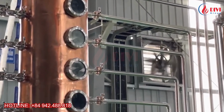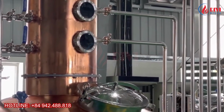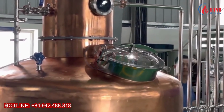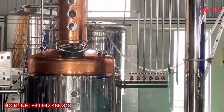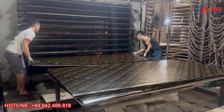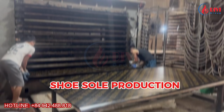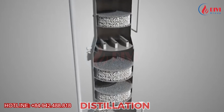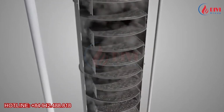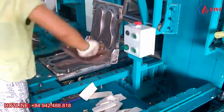Higher pressure means stricter equipment design requirements, greater safety risks, and higher investment costs. In contrast, thermal oil can be heated to 250 degrees Celsius, 280 degrees Celsius, or even 300 degrees Celsius, while operating at relatively low pressure. This makes thermal oil heaters ideal for production lines that require high temperatures without the need for high-pressure steam. Common applications include plywood production, hot pressing, shoe sole molding, mold heating, high-temperature drying, oil and chemical heating, distillation, and many other industrial processes. In hot pressing applications, maintaining a high and stable surface temperature is essential. A thermal oil heater is well suited to meet this requirement.